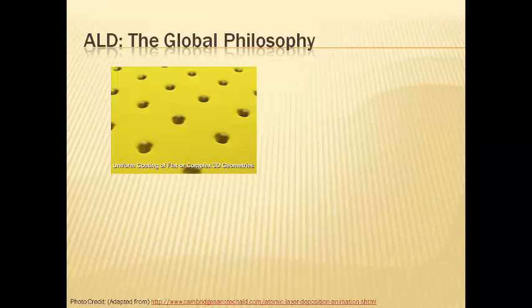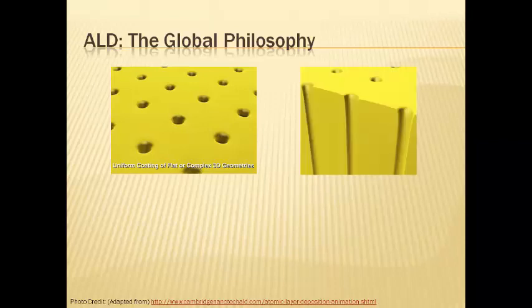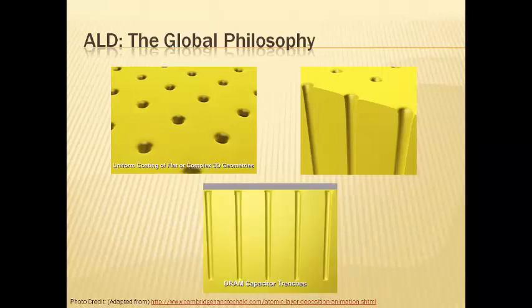Atomic layer deposition is a technique that can be used to provide a uniform, or better termed as conformal, coating of atomic or molecular layers on different surfaces, including complex 3D geometries, amorphous substrates, nanotubes, etc. Shown here is such a surface, and a cross-sectional view helps us understand the structure better. These essentially form the capacitor trenches of DRAM. The idea is to conformally coat the surface with some material, such as aluminium oxide.